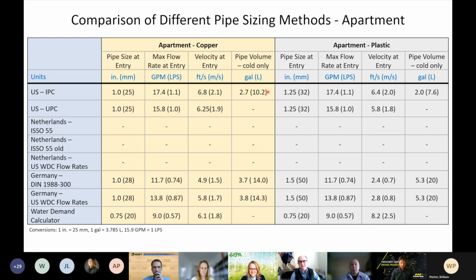Less is more. Everything with large volume has extra costs, if you will, in terms of water quality, you've got to clear out more water, as Jeremy pointed out. Well, from the entry to the apartment and then in the apartment. And so you lose energy whenever the hot water lines cool down. If there's more volume, more energy is lost at the end of the event that has to then be replaced at the beginning of the next.